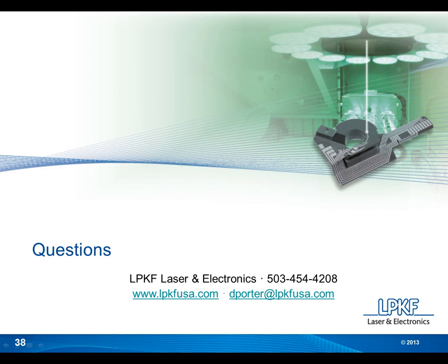We've seen in one of the earlier slides, there's many different manufacturers of LDS grade plastic material out there. And some materials can be reflow soldered with a lead-free solder. Some others cannot. For example, PCABS material is a very common material that we see in antenna applications, but it's a very low temperature material, so it's not necessarily the first choice when it comes to solder on it. If you want to solder on a part, then the choice probably goes more towards a PA66T or a PPA material, a nylon-based plastic that has higher temperature and is lead-free solder compatible.